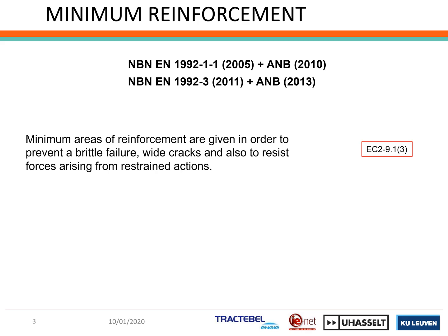Reinforcement due to restraint deformation is clearly regarded here as a minimum reinforcement and should therefore not be accumulated with reinforcement coming from external actions. However, reinforcement needed for overall temperature increase or decrease after the construction is built must be combined with other load cases.